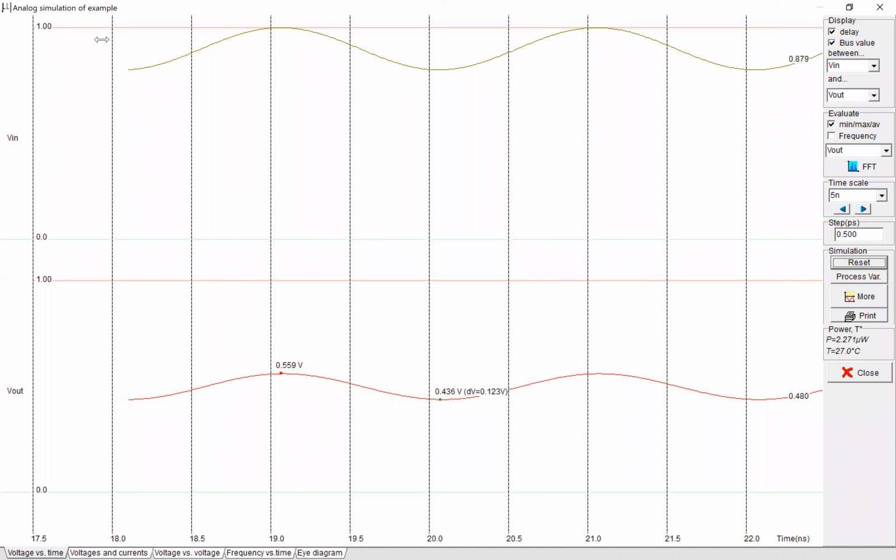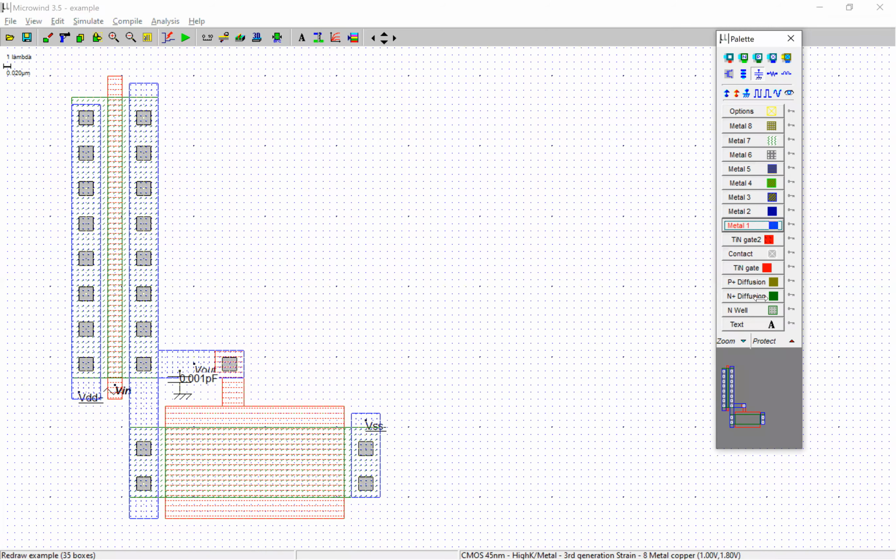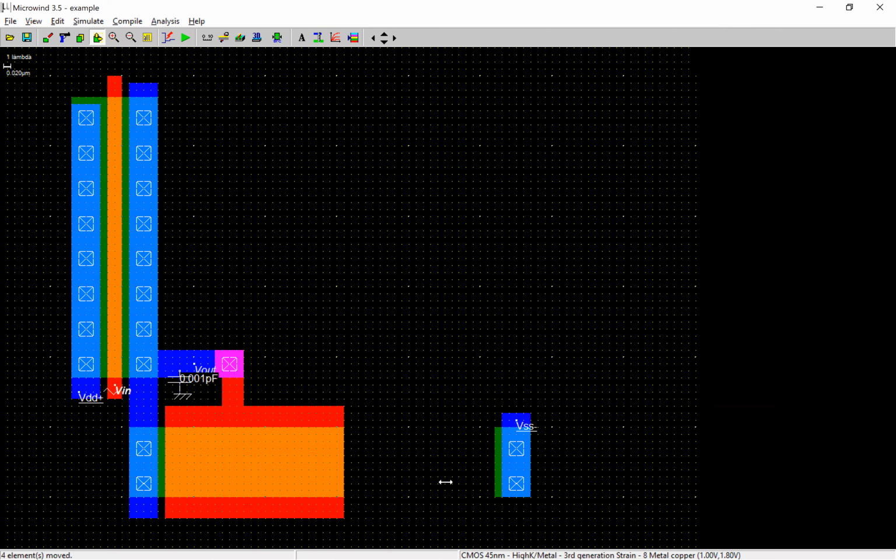So let me stretch move. What I do is just stretch this up, I increase the length. You can see that I've just shifted the diffusion and all this. So I take the diffusion, draw n diffusion, draw a box and join them. So what has happened? They have reached. At the same time, I can take the stretch move, click on the left line and extend it just before the metal line. Okay, maybe one step more.